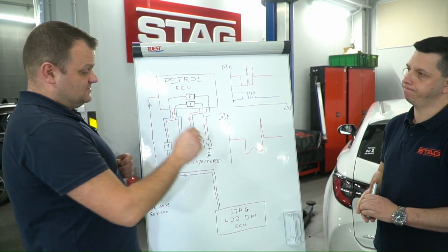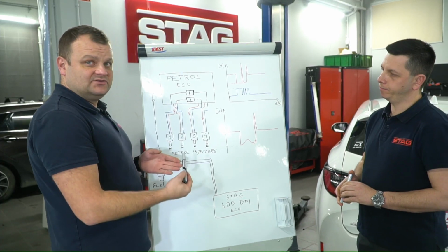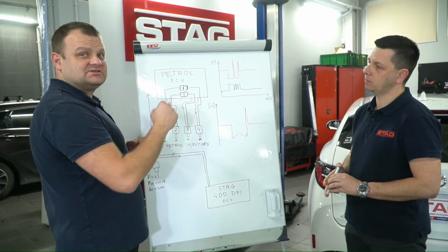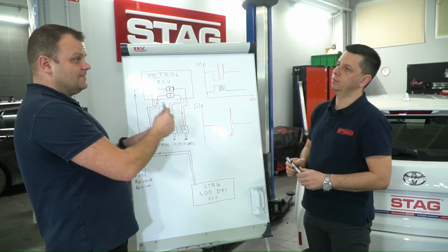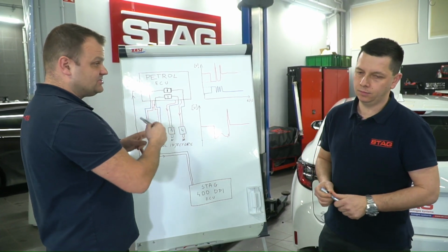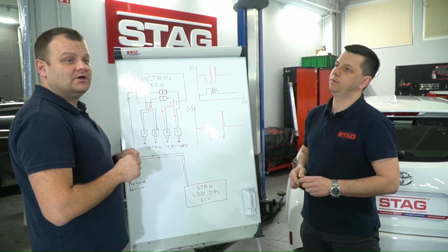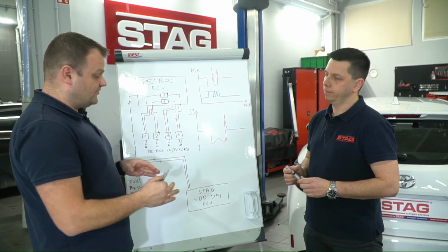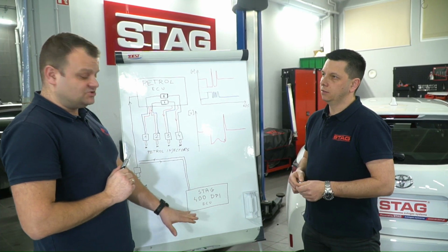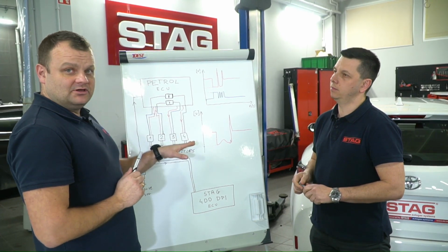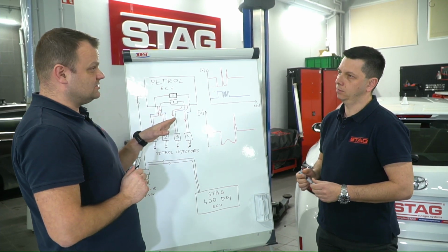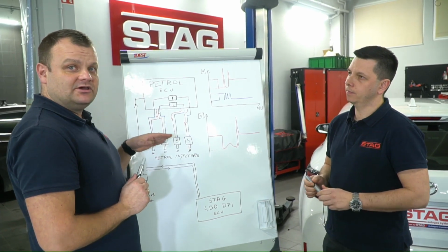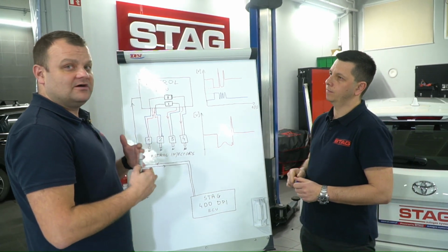Right. That's why the gas ECU is designed to ignore some of this noise in the signal because of the high voltage. So if you switch the connections, the problem will arise because of the algorithm inside the ECU. If we connect it properly, the Stag 400 will diagnose these noises and automatically apply a filter on it.